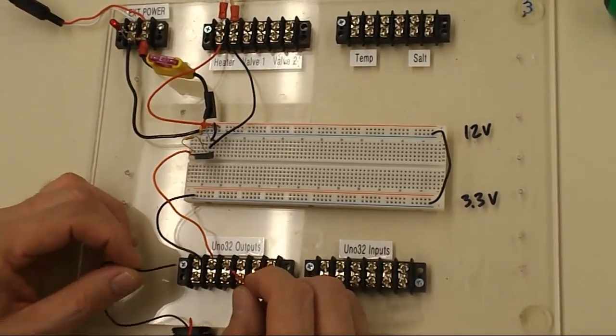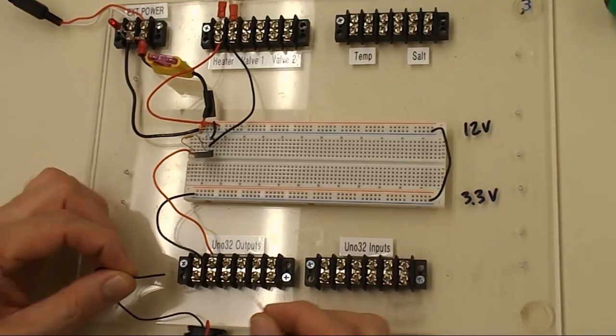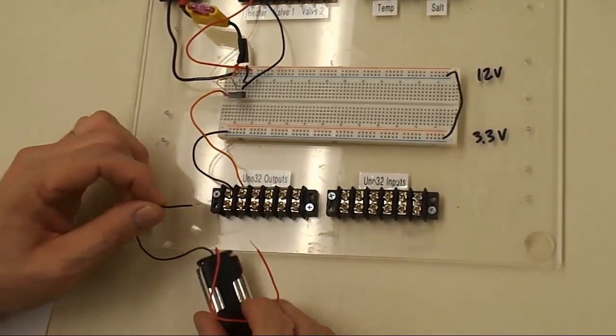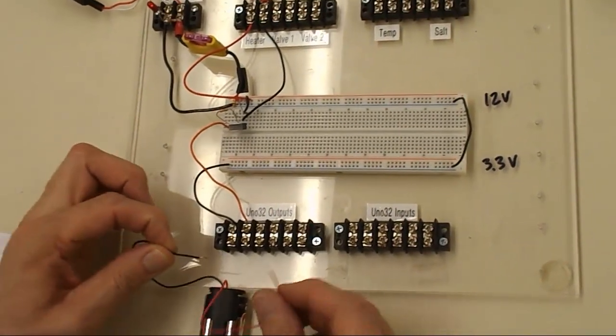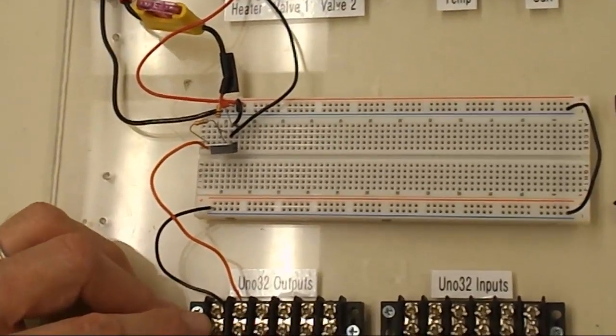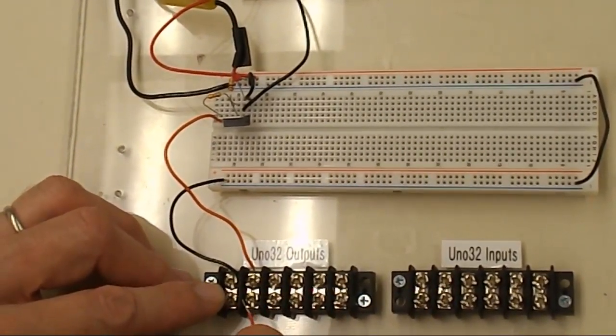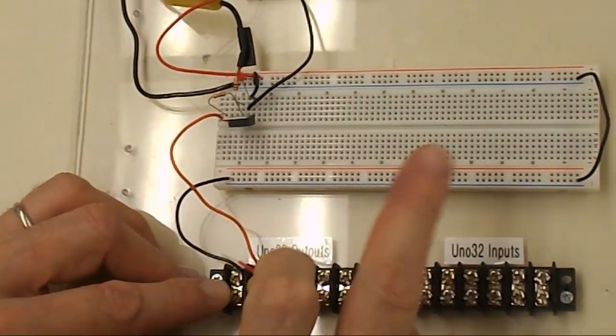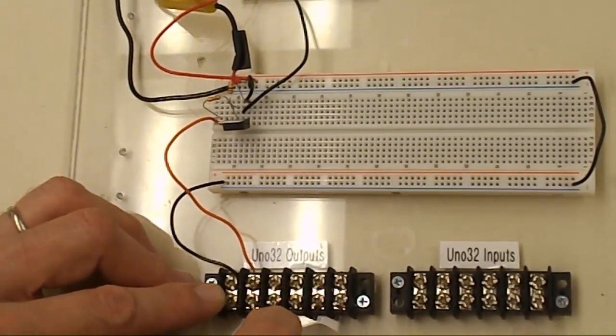So again, we're going to test the circuit using this 3 volt power supply made up of 2 AAs inserted correctly in this holder. So we've got ground and 3 volts, and I'll hold the ground against our ground terminal, and that goes over, and then we touch this here, and so you should see the LED light up and hear the solenoid valve operate.